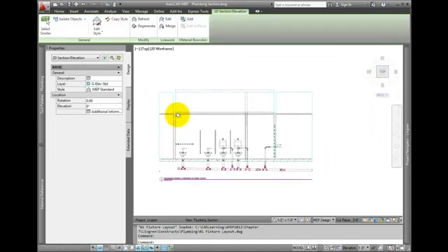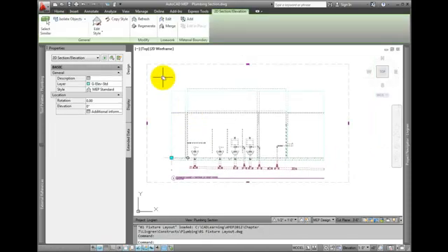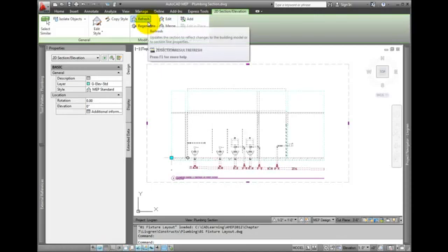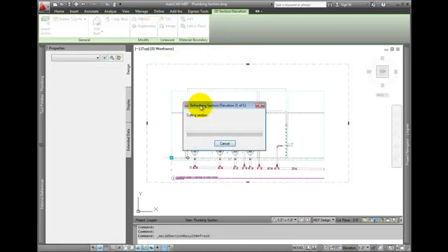Pick the section. From the 2D Elevation tab on the ribbon, select Refresh. Refresh updates what the section already has in it. If an item is deleted, modified, moved, has its layer properties changed, or the style is updated, the refresh is a quick update.